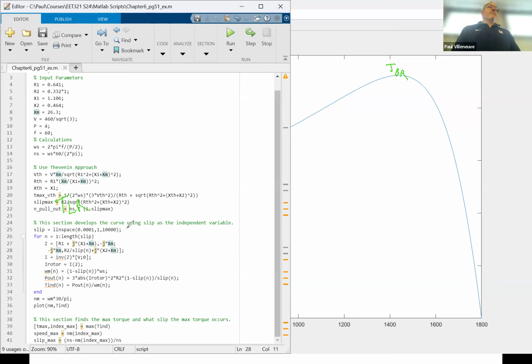But then how do you get it slower than that? You'd have to use a different dynamometer. The ones we have, once they start spinning slowly, they don't put out a constant amount of torque. They do a pretty good job at a decent speed, but once the speed starts to slow down, you can't get there from here.